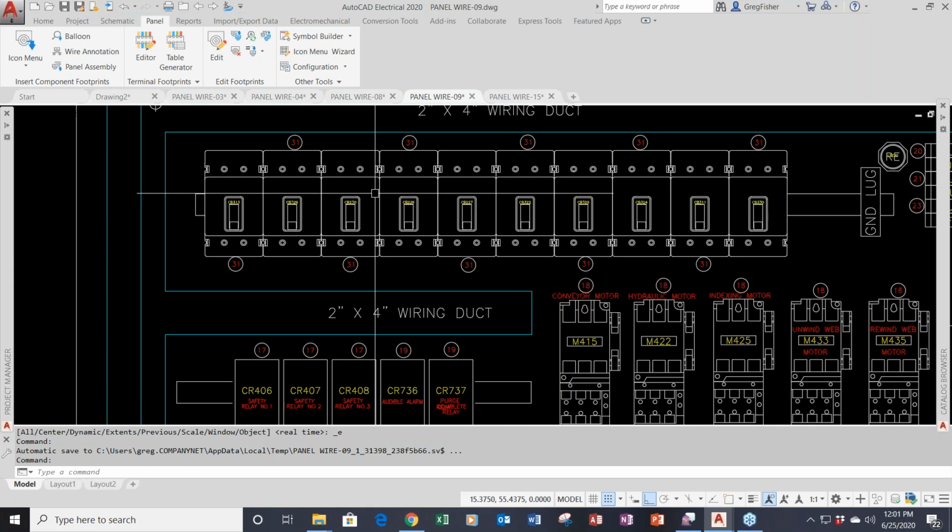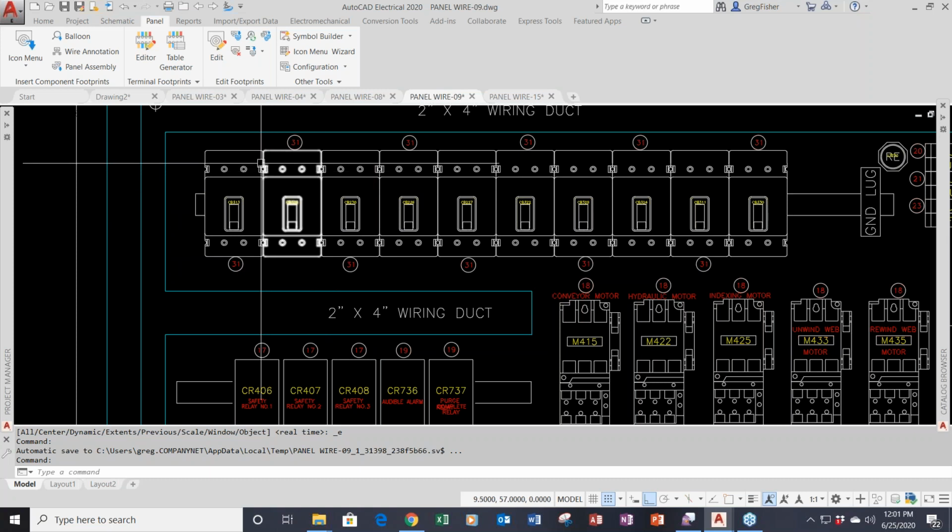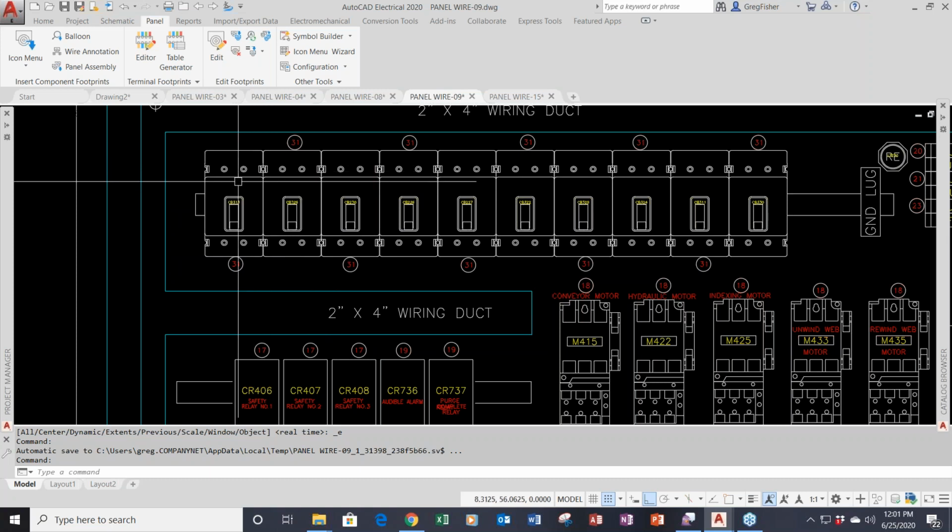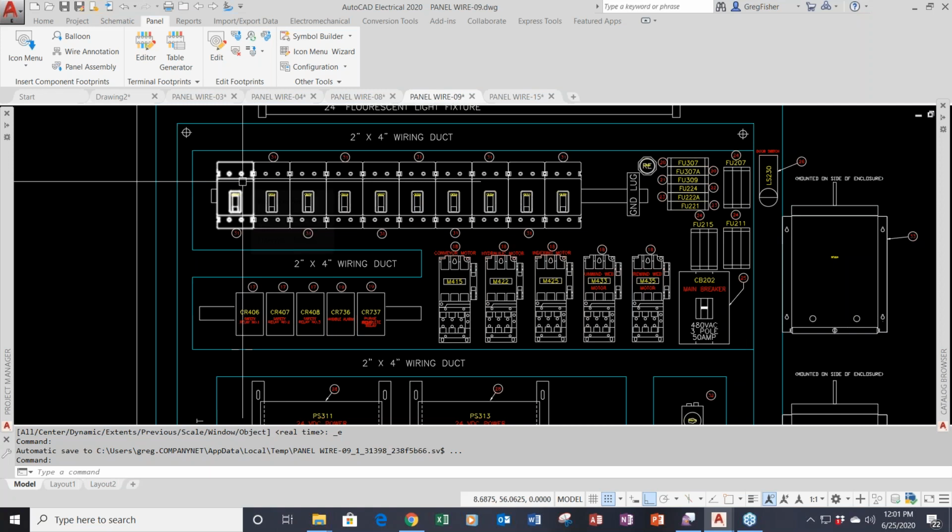And there's two ways you can go about it. You could have one footprint symbol and display the information right on the mechanical layout like this is here. I consider this my main panel drawing itself. Or you can have an additional footprint symbol that's representative of your original one. So if I take a look at this drawing right here, I did the latter. I created another footprint symbol to go along with what I'll call the master one.